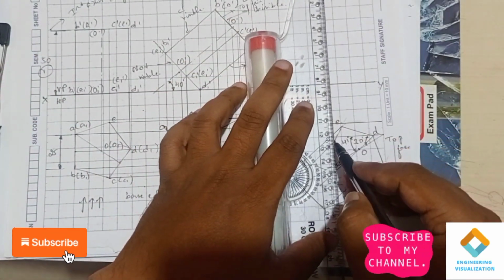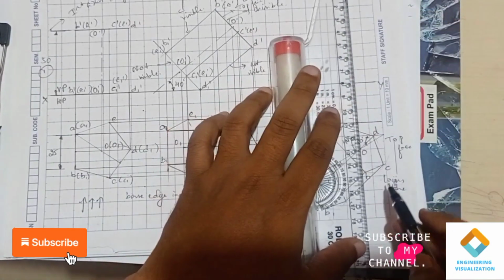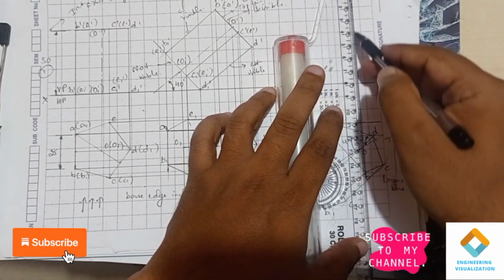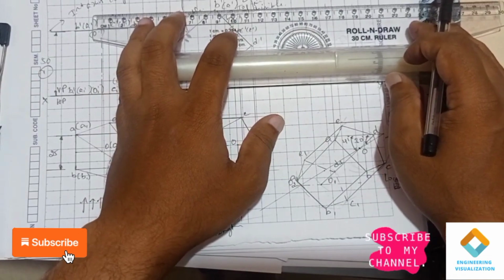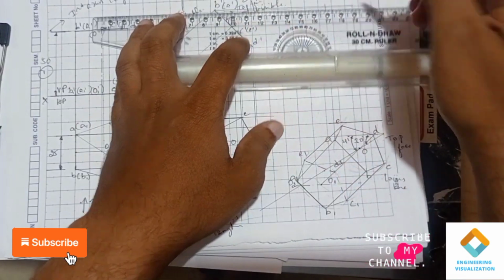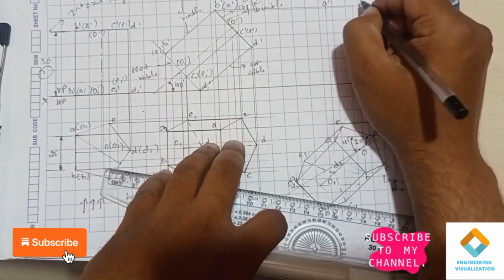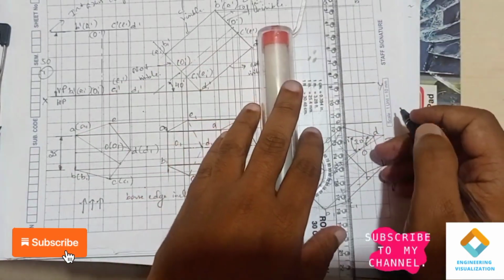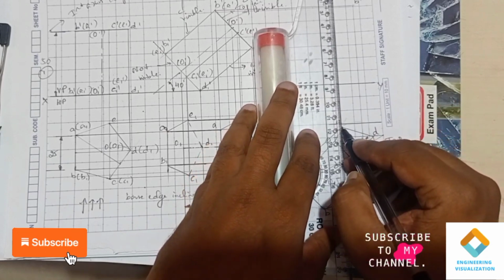So you can see here from A I am drawing a line here, projection line. A and B, vertical lines. Straight lines you just draw. Okay, don't get confused about whether it should be merging or not merging. No need to consider anything, just draw the horizontal and vertical straight lines. So these 2 points are nothing but A dash and B dash. Okay, now same way we will be drawing the projection lines from E and C.